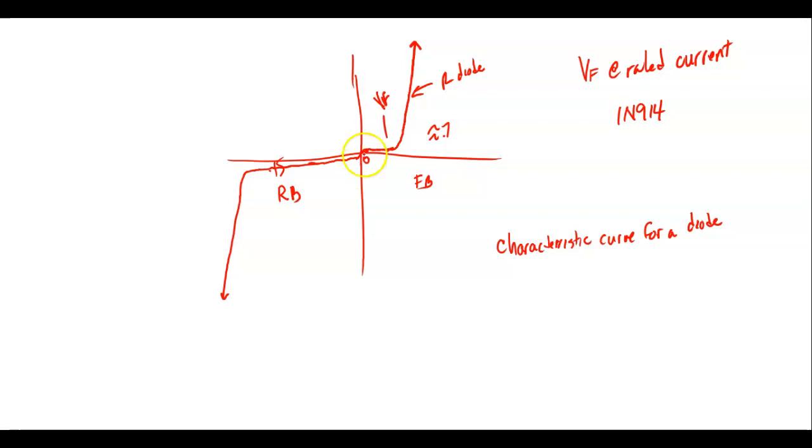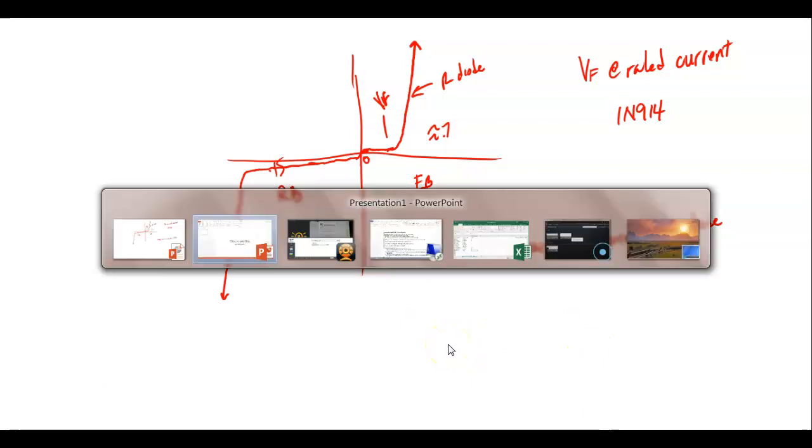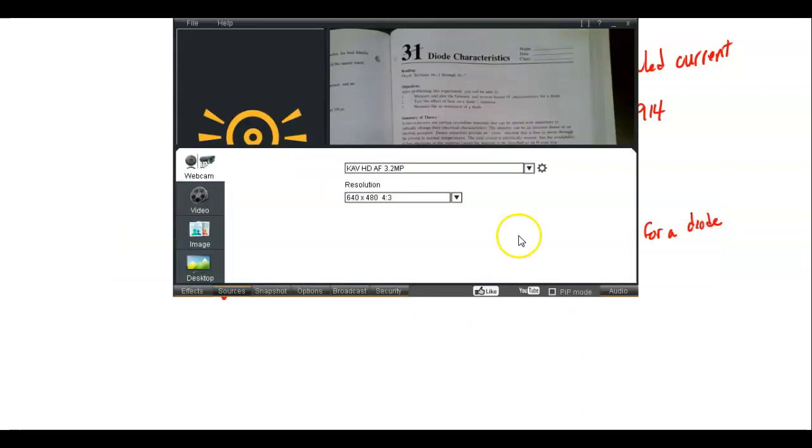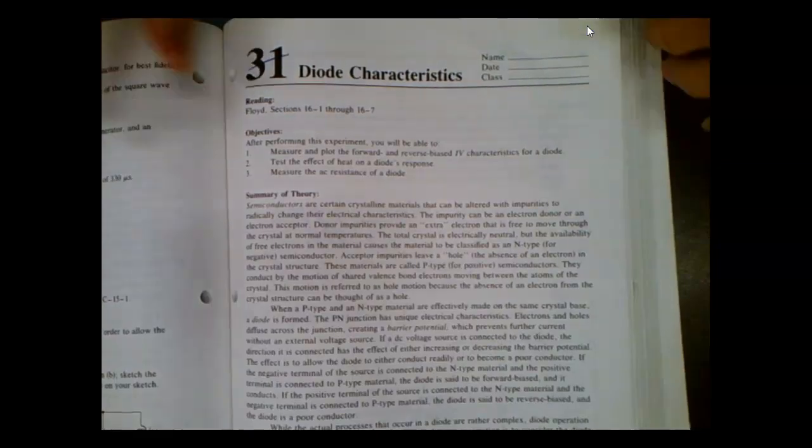So what we're going to do, guys, you're actually going to graph this out. Now if we look at the actual circuit, first we don't measure resistors, we use their color-coded values. Don't worry about that. We understand that our calculations will be perfect, but our measurements are not going to be exactly the same due to the tolerances of the resistors. Just X it out just like I did right here.